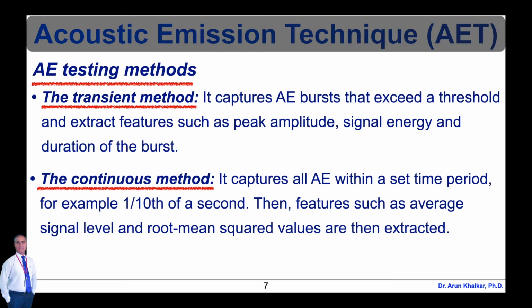Acoustic emission testing can be conducted in a laboratory as well as in field conditions, over both relatively short durations such as a few hours and longer durations such as a few months. Wireless data relay methods make it possible to analyze the data remotely.